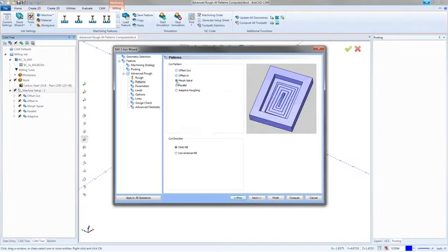The next one we have is a morph spiral. Now, the morph spiral is really cool because it doesn't have any sort of linking on it. It doesn't need them. It morphs the tool path so that it doesn't need to link. The tool path naturally just runs into its next cut just based on an angle that's in there. And it's kind of messy looking. It's very tough to see what's going on sometimes when you do use this one. Like I said, I have an example. I'll show it to you. But it's a very good tool path.